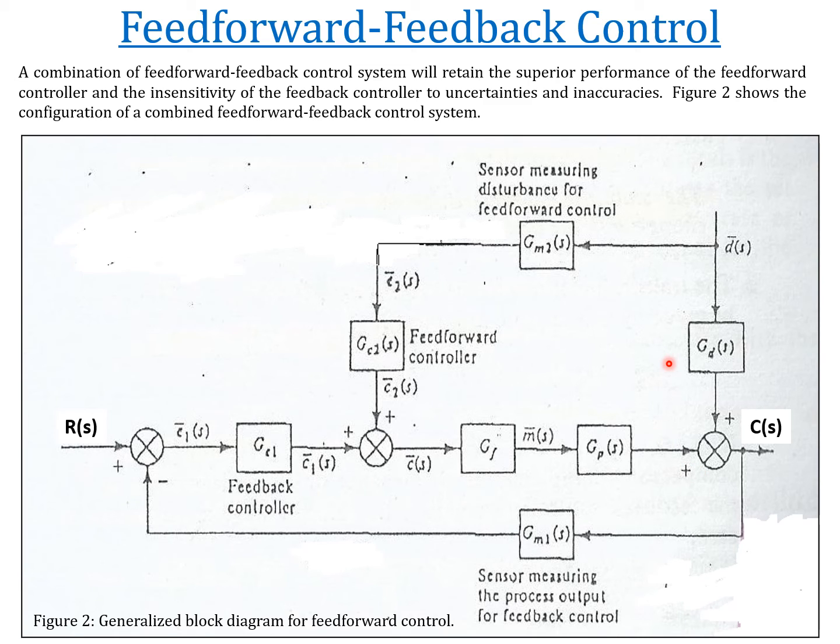It comes under the classical advanced control method. Because why? Because the feedforward controller is not a standard controller. This is based on the model that we've seen before, the set point part and the feedforward part. So it's a different type of controller. It's not PID definitely, but the feedback controller is still a PID. It can be a PI normally or PID controller. So it's a combination of the conventional process control and the advanced part, which is the feedforward controller.